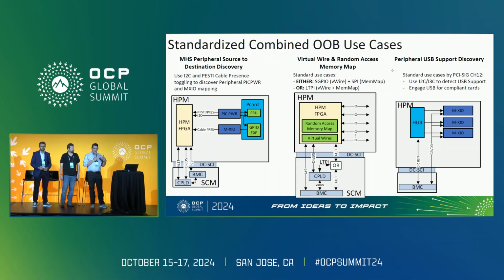That's an easy one in terms of discovery and then comparing the compatibility of the system wiring and the add-in card wiring. But this concept goes all across the board in terms of understanding what you're coupled to, compatibility check, and then engagement of the function that you've agreed upon. So that's kind of a common theme, and we've put into the PCI base spec 6.2 those common sets of rules that we're now trying to build on, as we're trying to make every wire as useful as possible and not just inert DC or toggles every once in a while. So that's a basic concept.